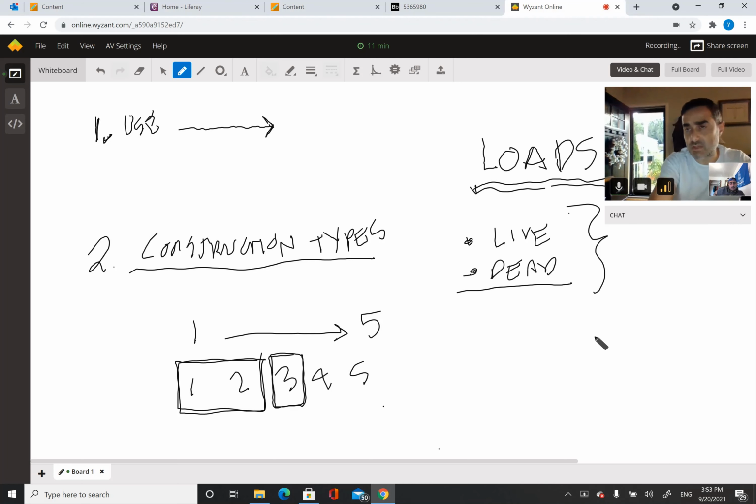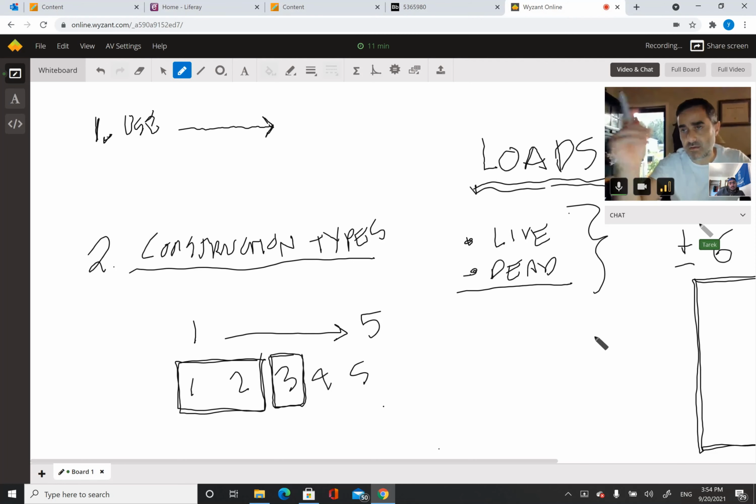Do you know what that means? Do you remember that from structures? Heavy timber construction means that the members are engineered wood, with member sizes that are more than 6 by 12, plus or minus. And there's a unique property to these. It's glue lam, for example.